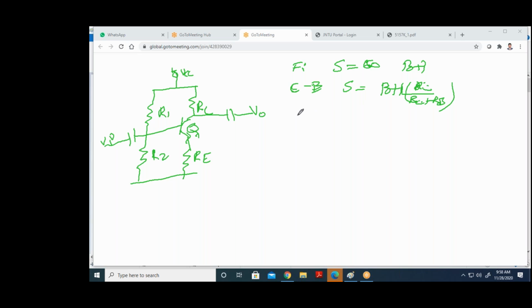Again emitter resistor also same. Only voltage divider bias, here stability is equal to 1. So this is a very important point. But whenever input signal is connected to the voltage divider bias, this input, which one? AC signal. Example, I am taking here 20 millivolts. AC or DC? 20 millivolts, AC signal, sinusoidal signal.